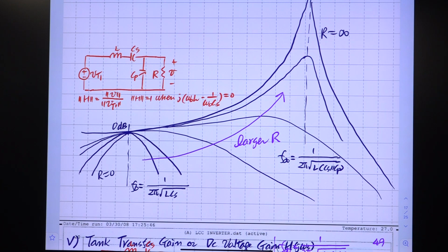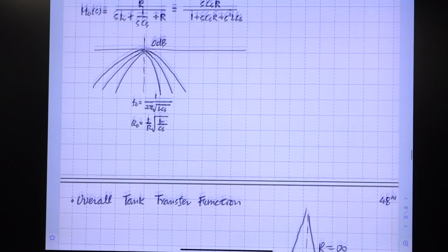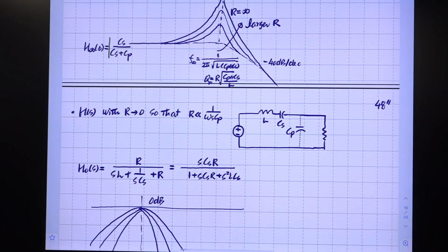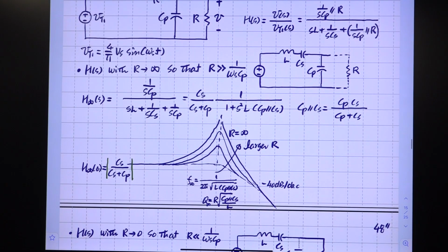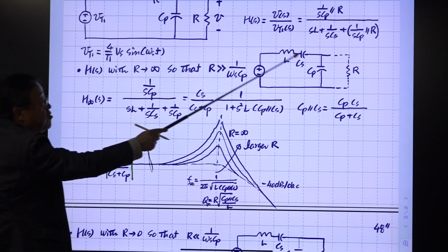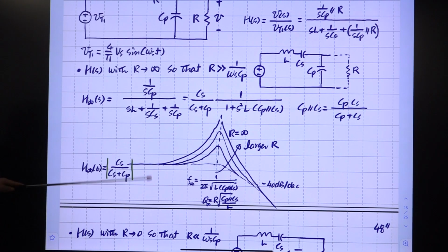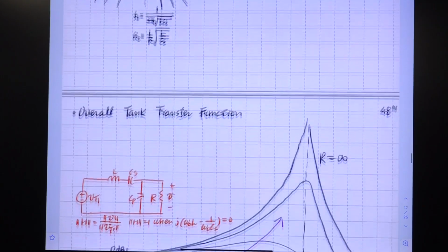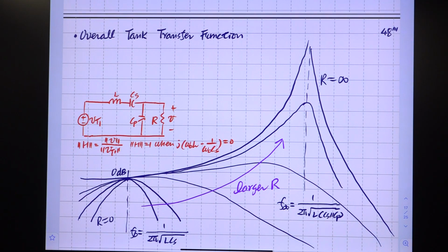So this is the picture. Oh, okay, I forgot to mention this. At low frequencies, we have just voltage division. At low frequency, this is shorted. You have two capacitors. So the division factor is this. The low frequency gain, maybe CP is large. No, CS is very large. Then CP, there will be the 0 dB line. It goes up like this. So if you merge them together, you have this kind of characteristics. Okay, so this is the general feature of this voltage gain curve.